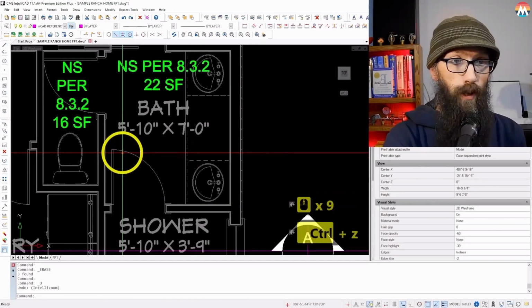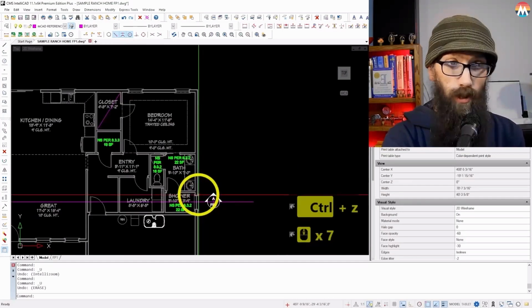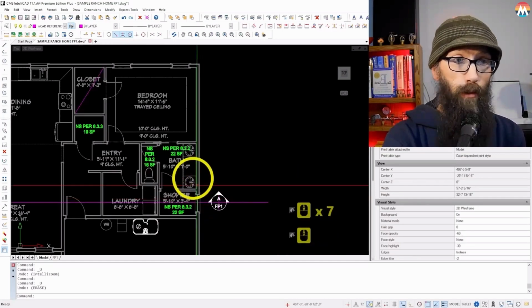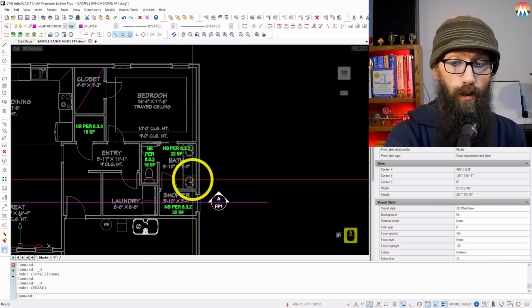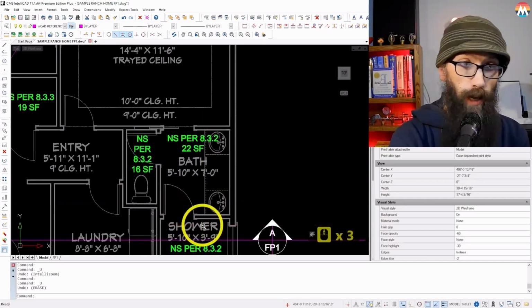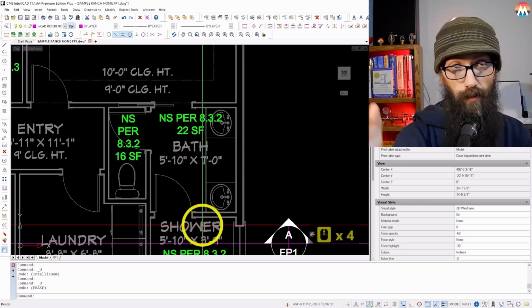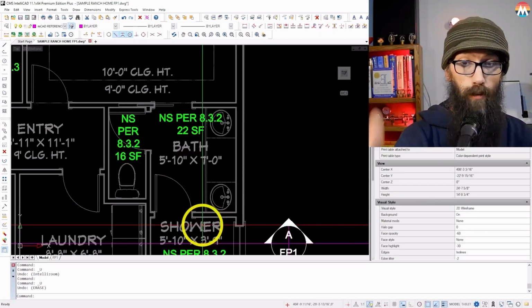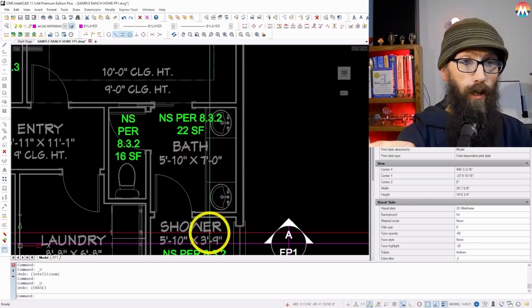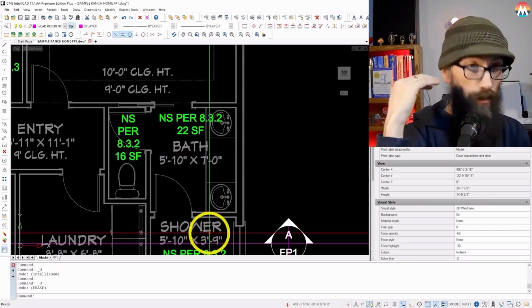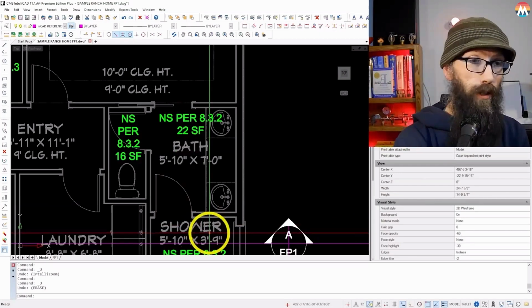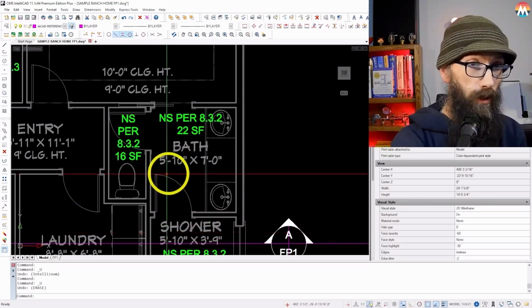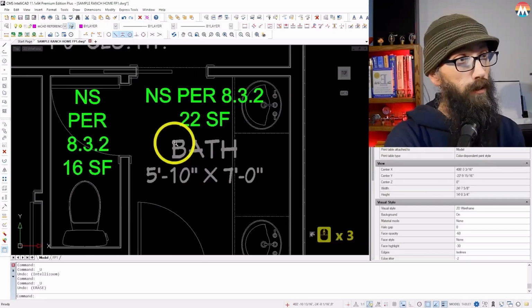So you have to be very aware of what you have selected all the time before you go into a move command. You think you may have just one thing selected, but you may have something else from previous that you've forgotten about. So before you go ahead and start your new command, I just automatically am hitting escape to make sure I don't have anything that I forgot about selected.